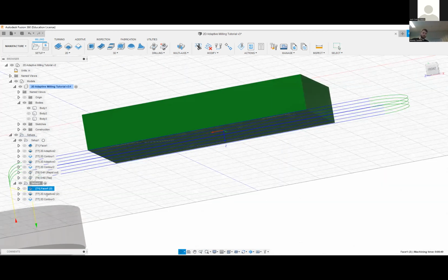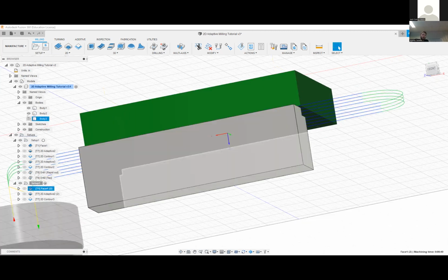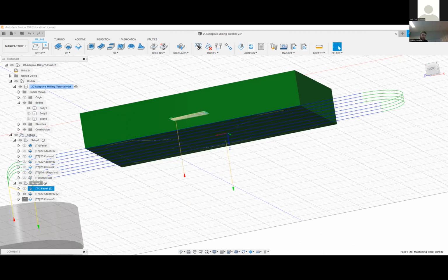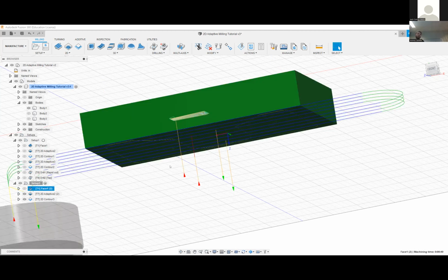On the lathe, it would be its own thing. Even if there wasn't that cut in the middle, you would still have to turn it over. If there was no cut in the middle, my tool path would simply be this on the backside. And oftentimes I'll have a really complex part that I just chuck in upside down and run a facing pass along the backside. I have to do that for every part I make. There's not really a way to avoid that. Yeah, I program it. I don't do it by hand.